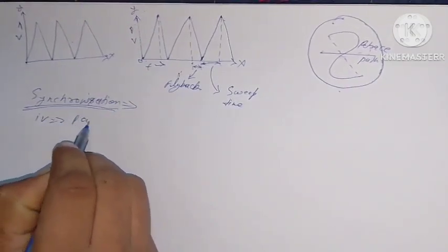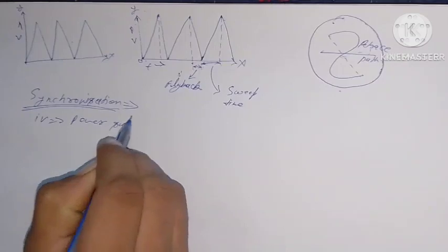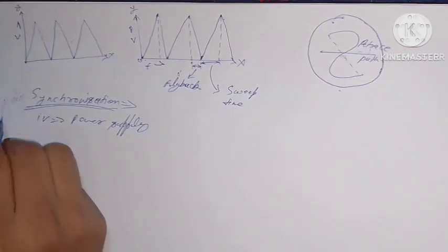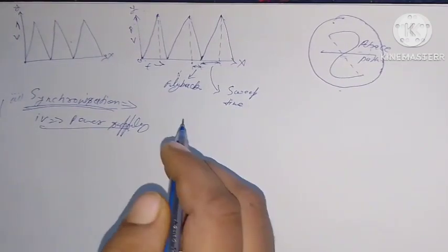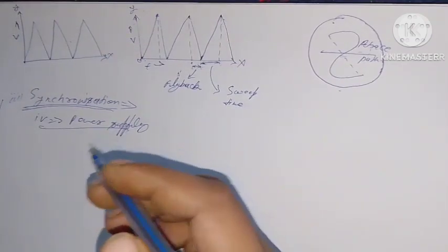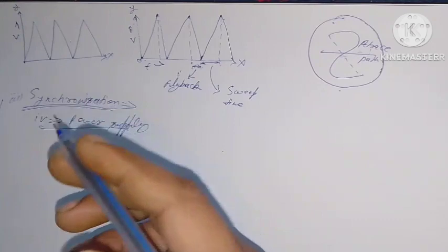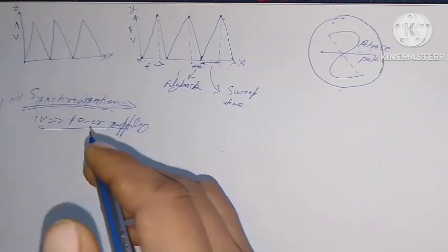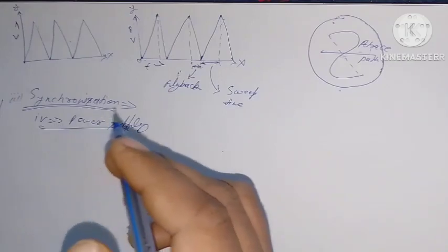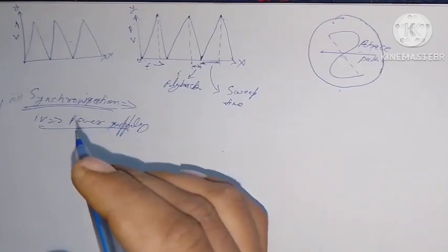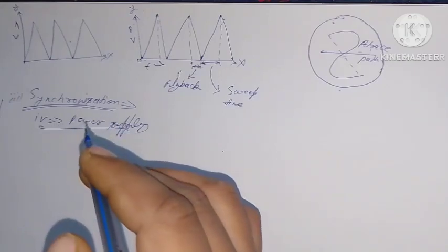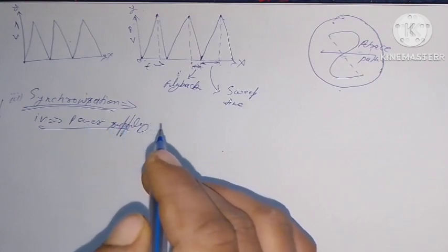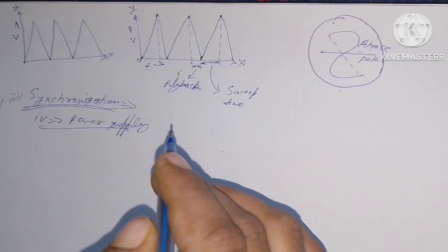Okay. Fourth, power supply. The power supply provides the high voltage for the cathode ray tube filament, voltage for vacuum tubes, if any, and low voltage for other valves or transistors in the circuit.